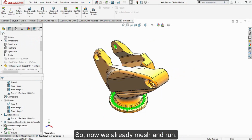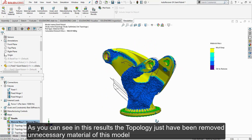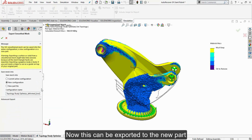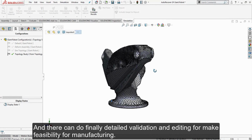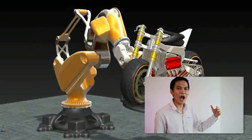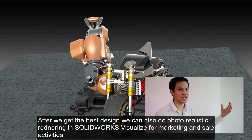So now we are ready to run. As you can see in this result, the topology study has removed unnecessary material from this model, and a new geometry is proposed by the software. Now this can be exported to a new part, and we can finally do detailing, validation and editing to make it feasible for manufacturing. After we get the best design, we can also do photorealistic rendering in SOLIDWORKS Visualize for marketing and sales activities.